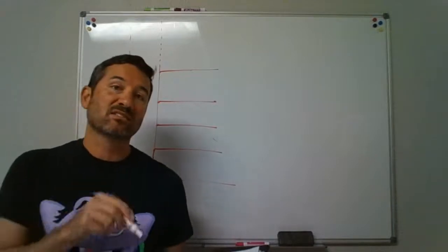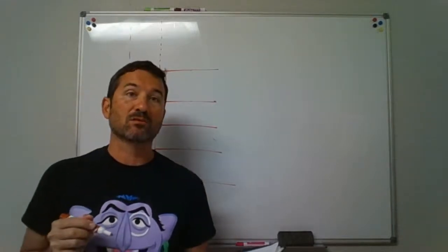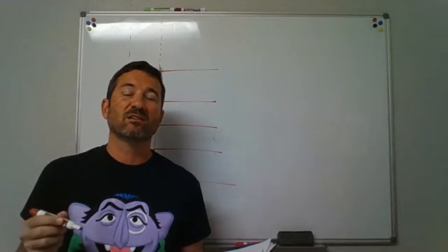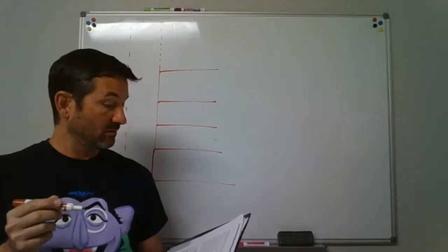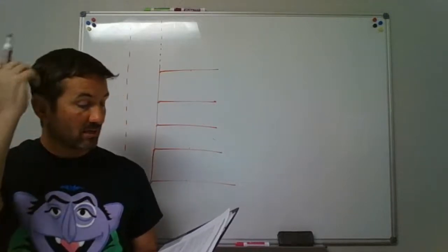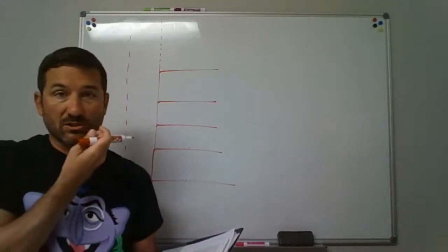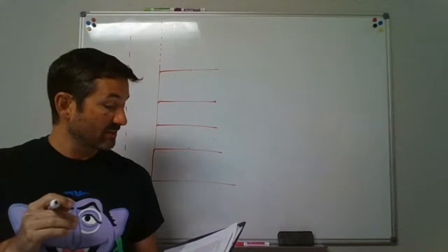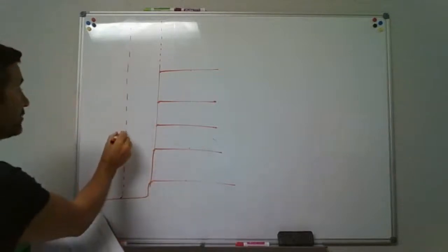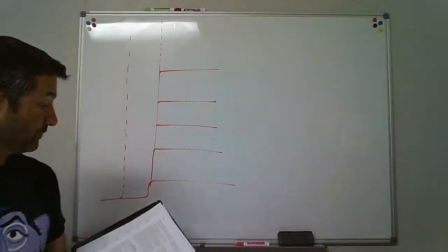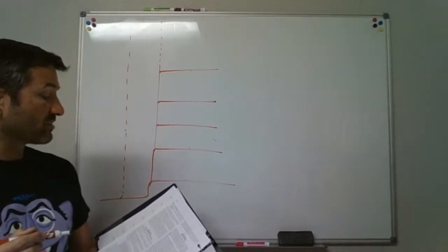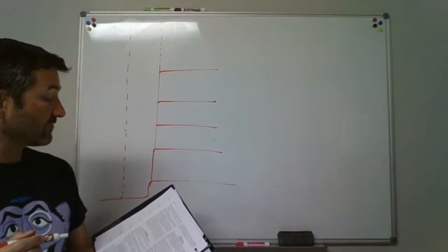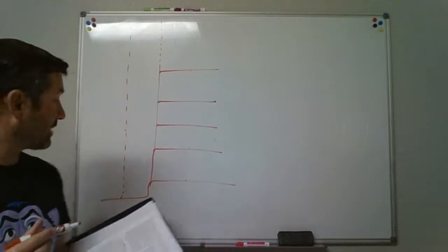The vent connection at the base. Where does the vent stack connect? We already talked about the main vent, or that stack. Where's that going to connect to? And that's to the building drain, or a branch of the building drain not less than 3 inches in size. But now we're going to say, well, where does this one, the vent stack, connect to? And this is 904.4. Vent stacks shall connect to the base of the drainage stack. Okay, the base of the drainage stack.